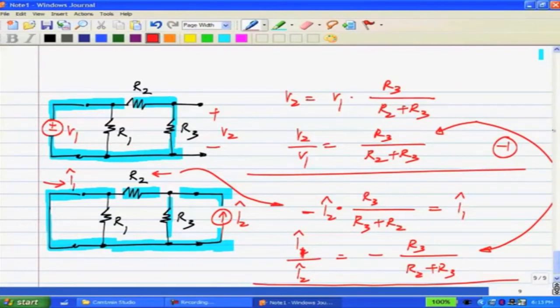Now, it turns out that this reciprocity theorem is very useful in many practical situations, and one such situation is where you have a number of sources in a circuit and you want to calculate the response at a given point, whether it is current or a voltage between 2 points. Now, instead of calculating the response from multiple sources, what you can do is use reciprocity, interchange the locations of the source and the response, and calculate all these responses to a single source, which is definitely easier.